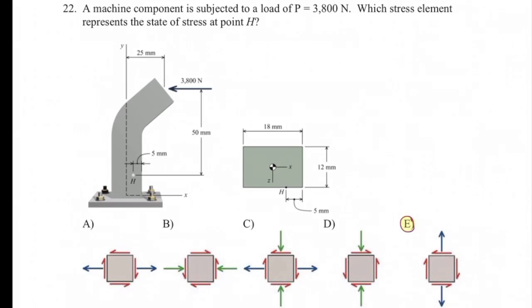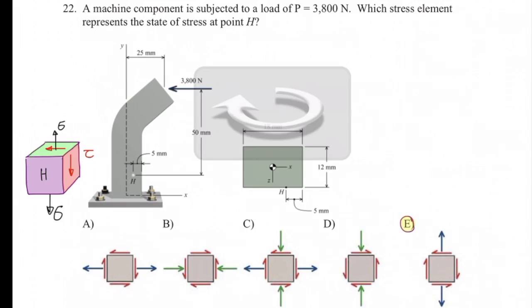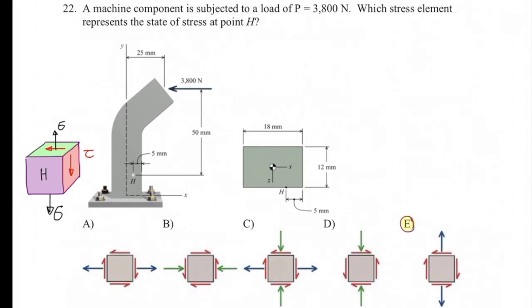Once we cut this element and take out the element, I would see this three-dimensional stress element. The stresses, both shear and normal, are just acting on the top surface of that cut section, because when we are talking about the stresses developed by combined loading, they are always produced on the cut section of the beam.